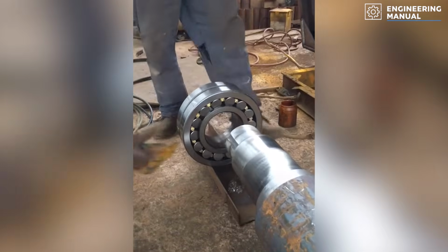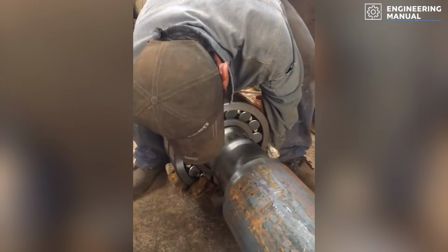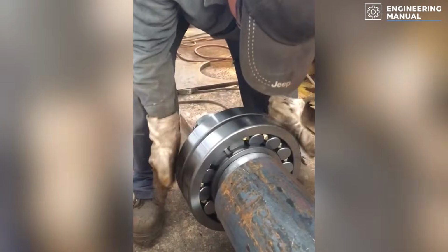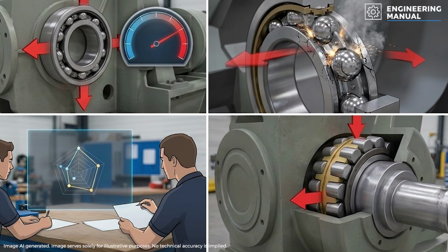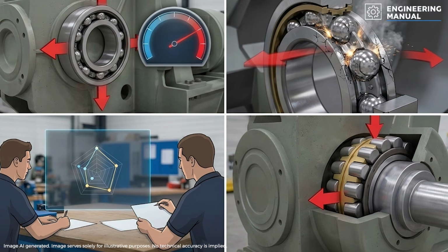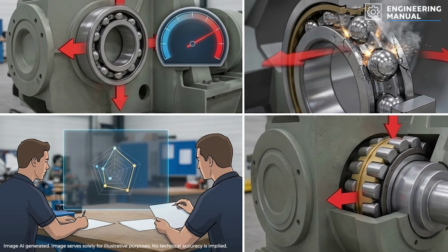Large industrial roller bearings therefore require carefully engineered lubrication systems, not simply to reduce friction, but to remove heat before it destroys the lubricant itself. Whenever enormous radial loads dominate the design, engineers willingly accept those trade-offs, because the alternative is a ball bearing that simply cannot carry the load.